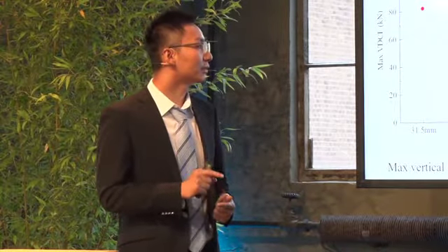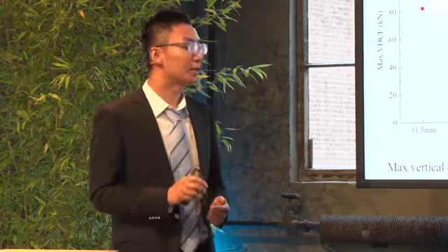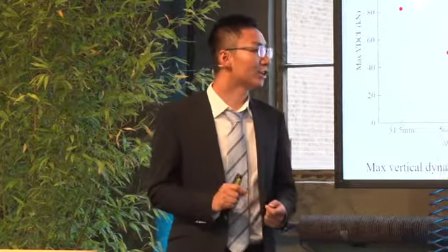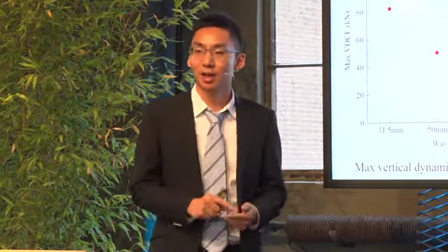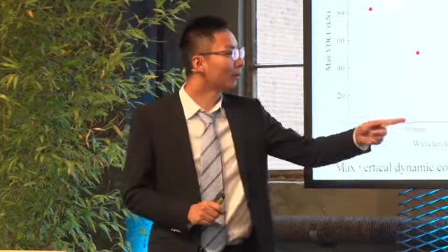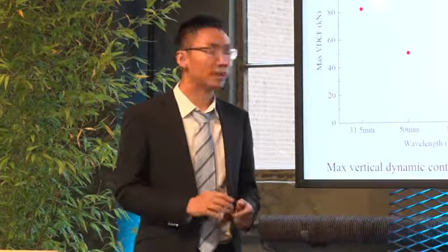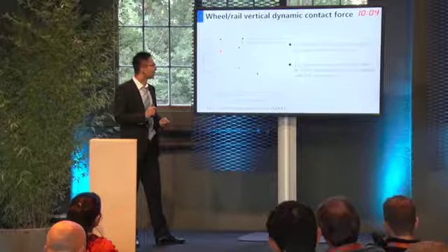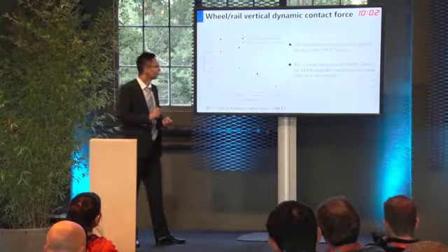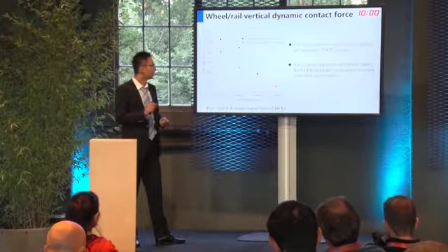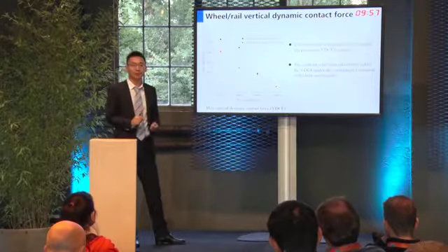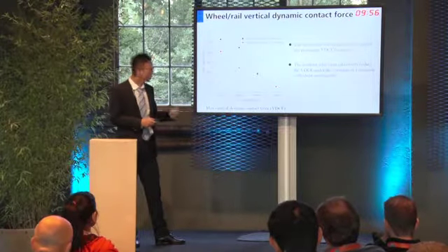It is further seen that the resilient wheel can effectively reduce the dynamic force under corrugation excitation with the short wavelength, while the effect becomes negligible with the long wavelength. This is related to the radial decoupling frequency of the resilient wheel, and we will show it later.